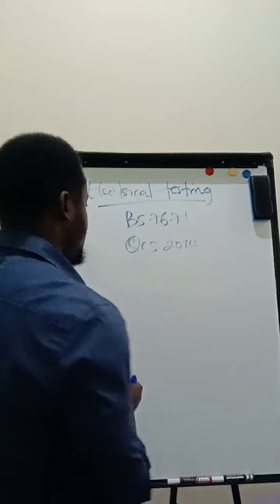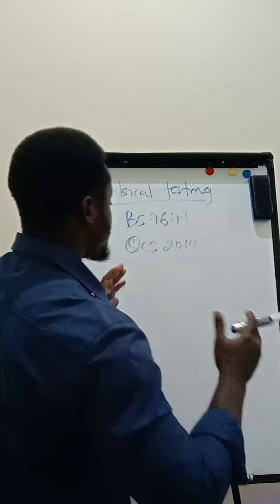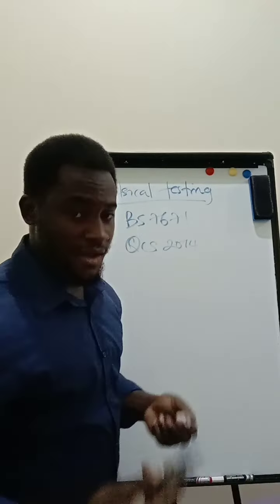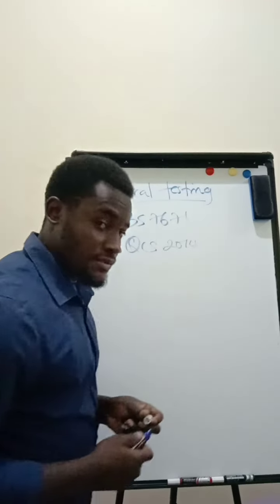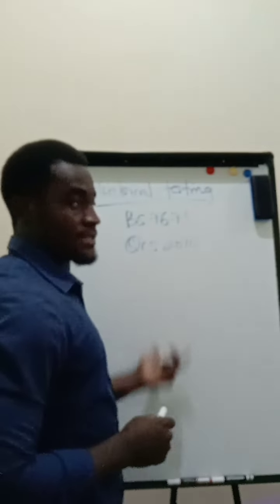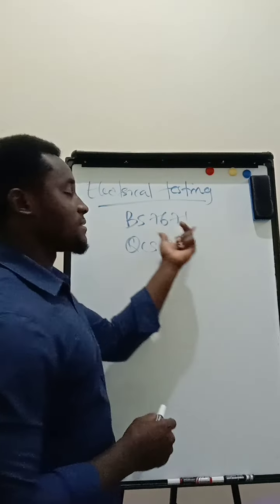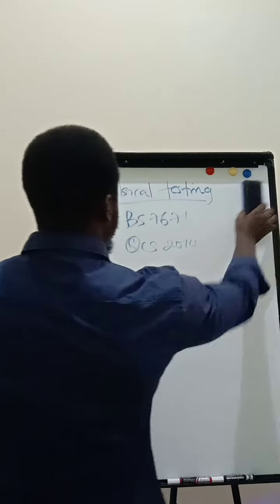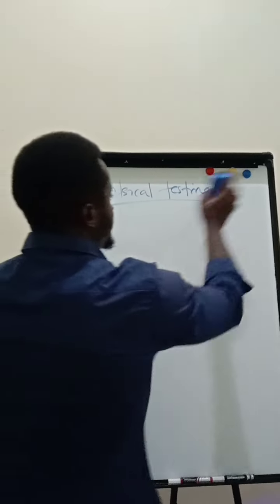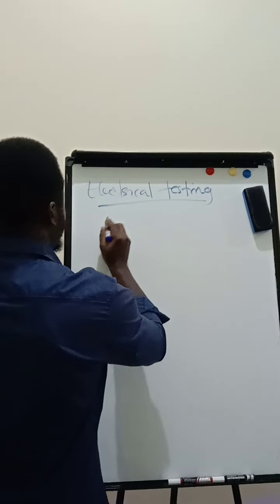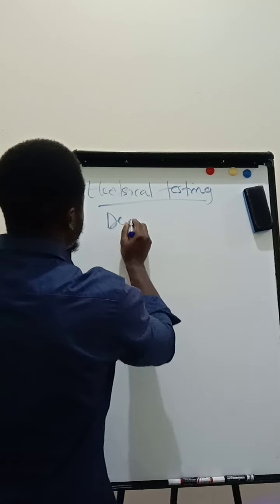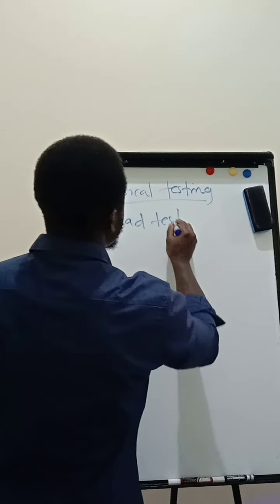So as per BS7671, like I did mention, I will divide the different tests into two parts, which are the dead test and the live test. For BS7671, which I have to follow, and also for QCS 2014, we find these different tests, which I'll mention as we keep moving. Okay, I will start with the dead test.